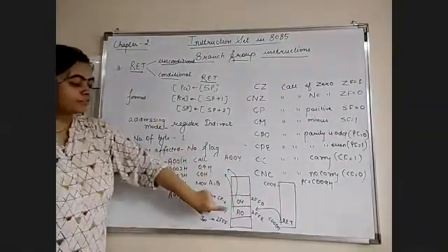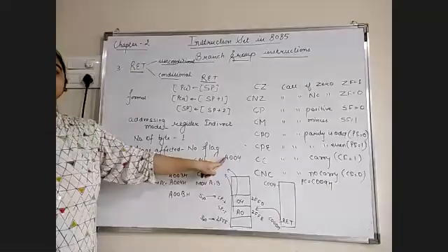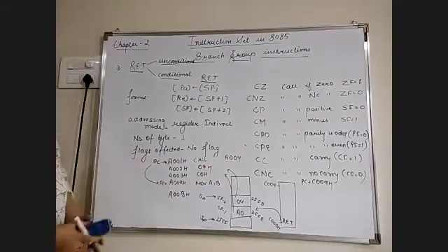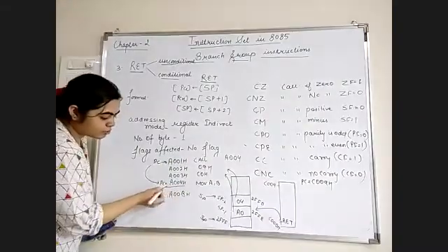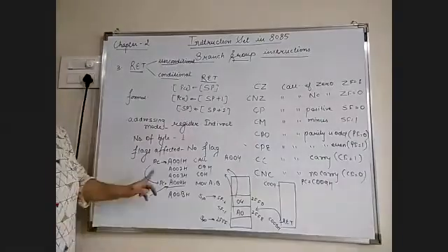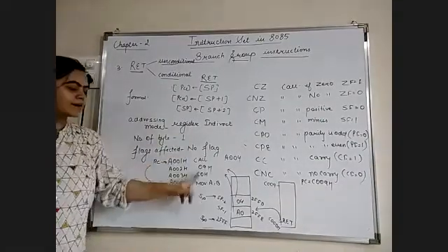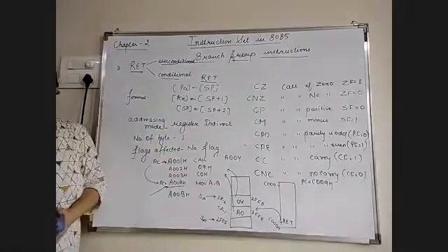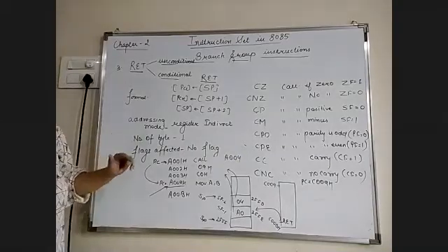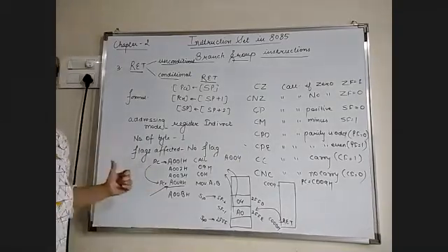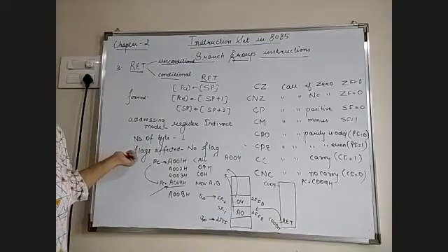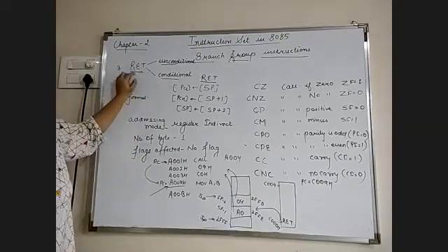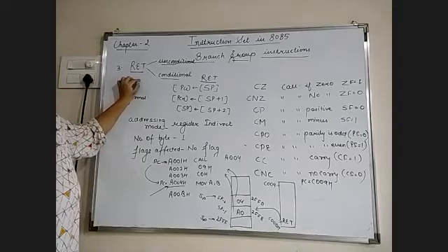After popping these contents, the microprocessor will jump to this memory location, which is part of the main program. So the microprocessor gets back to memory location A004 and starts executing the program from this location. This is about the return statement. During call, a push operation is performed, and during return, a pop operation is performed. Return statement alone will not work, it will work with the call statement.